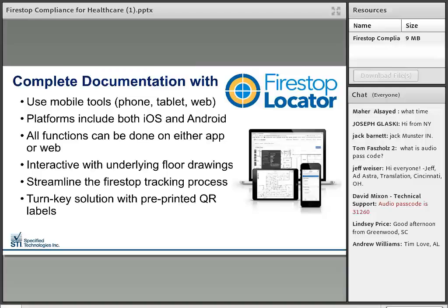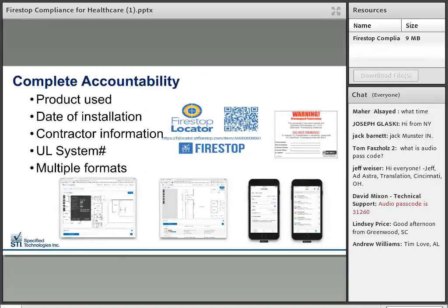And you can see here that you can either use a QR code or maybe you use some sort of a sticker like you see here. So if you look here, this is the older process, and at the very least, a label, if you're using the 3-ring binder type process, this would be something that would be applied to the wall. I talked about accountability. If I have to sign my work, I'm probably going to take a little bit more time and create the right detail. Or you enter the information in the locator and you have a QR barcode. So if you and the inspector are walking through the building, or you're interested in knowing what's been done at a particular location, you could actually scan that barcode and see all the information that was entered associated with that penetration.